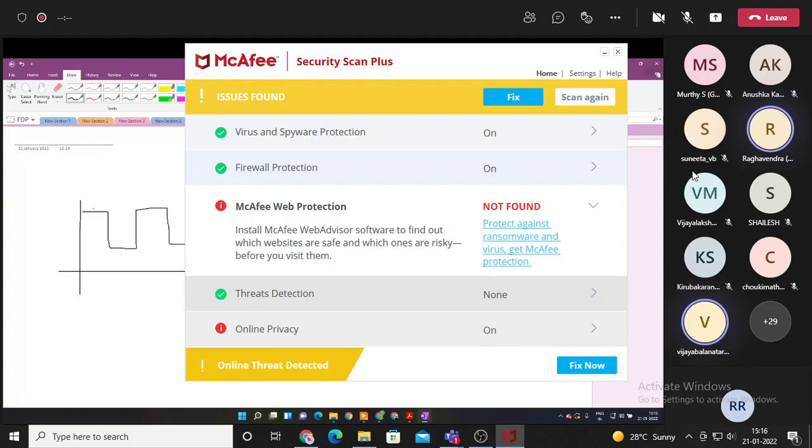Take an average of the power throughout. So average of this plus average of this plus average of this, and so on. The average will lie somewhere over here. So I'll keep this as my threshold. Anything going above this, I will consider a 1. Anything going below this, I will consider a 0.